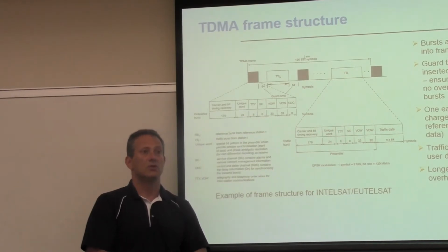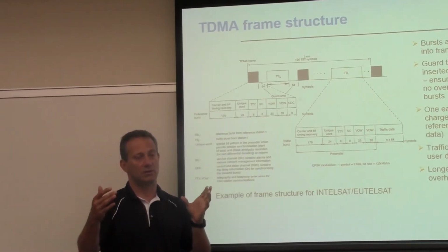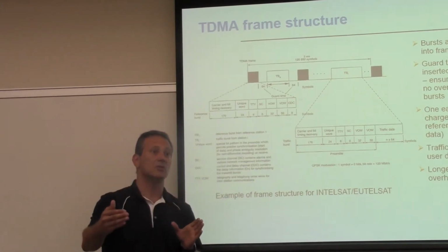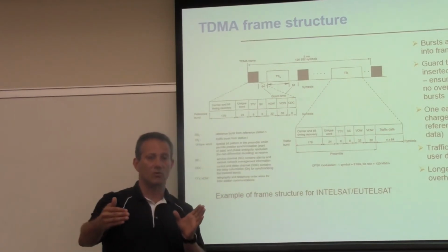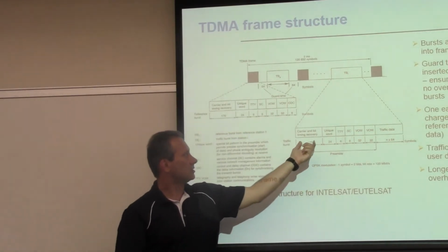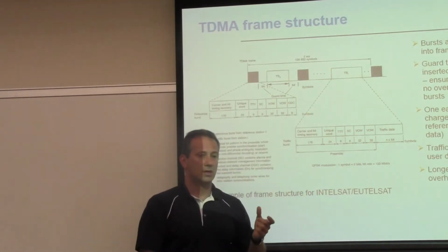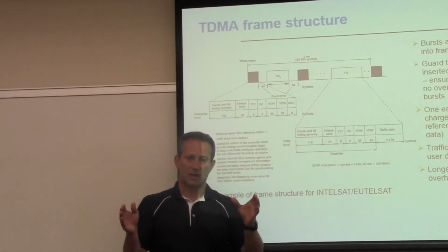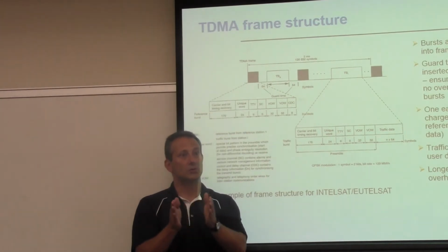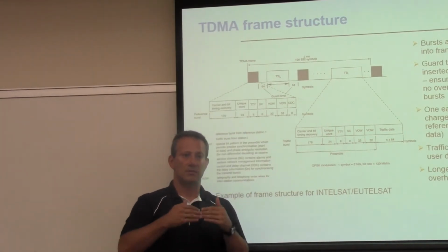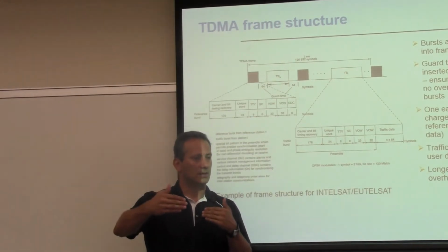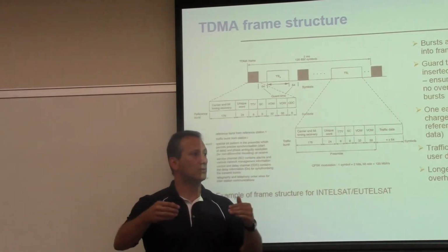And this is done through what is called a unique word. Or in other words, you would assign an identifier to a base station, which is usually some specific code. So when you decode that code, you know which Earth station you are listening to. But it goes more than that. This code, referred to here as a unique word, is a special kind of code that allows you to detect the beginning and end of your symbols. Do your symbol synchronization. Remember, when you synchronize to carrier, all you did is detect the frequency and the phase of the I and Q components.